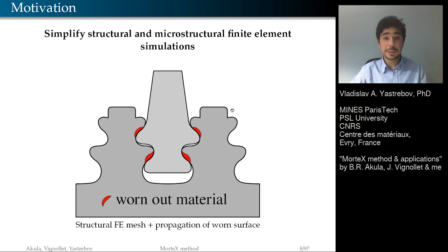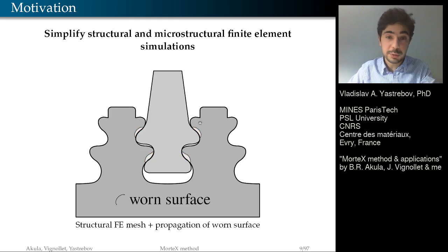And sometimes you are faced with complicated wear problems in which material is removed, and we need to deal with the newly formed surfaces, which are not the original surfaces of the mesh. So it's important to be able to create new surfaces and get rid of the old ones. It's not easy to do, and so we need to deal with this newly defined geometry.